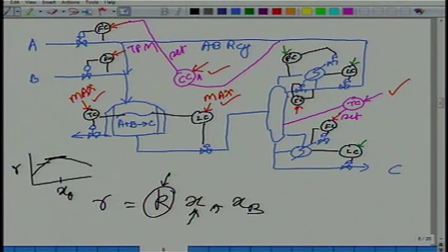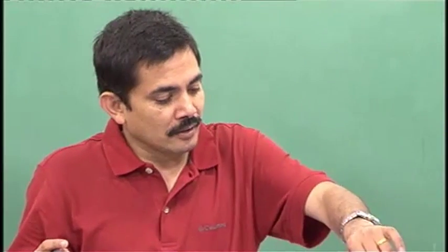Now this throughput manipulator may be under level control from an upstream process, in which case it's not in your hands. An upstream process is setting it. How much should the plant produce? Maybe your management is telling you, in which case the set point here is again fixed. It could be a real degree of freedom where you have the flexibility of choosing what is my optimal throughput.